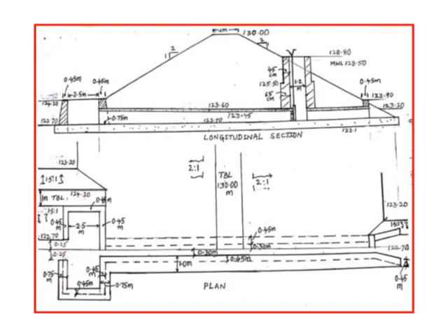So this is the drawing part which pertains to the design sheet. I told you that this is the regulating arrangement. A person can come over here and go here and simply regulate, and this is the diaphragm wall that you have provided. So there is a 45 centimeter opening, and then the shutter gates are provided, which are regulated here. So a person can come here, simply lift it, and then the water enters here.